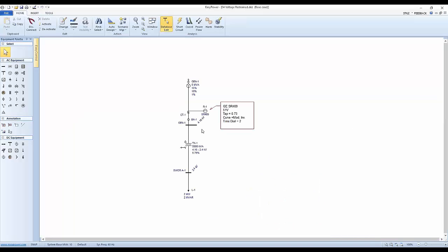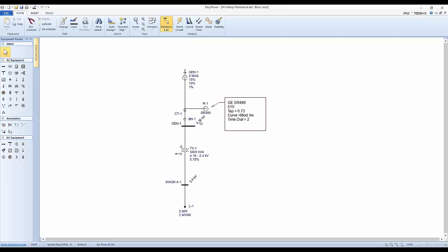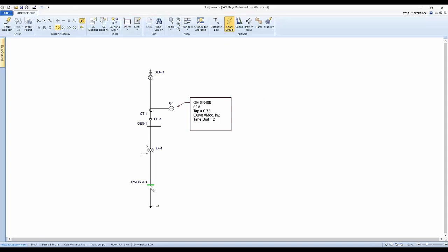There's another type of differential relay that's utilized when we have variable voltage, and very frequently this is used in a generator protection scheme. What it amounts to here is when I go to short circuit and fault this particular bus downstream, I may end up with some sort of a fault condition that's dependent upon the variations in the settings because of the voltage sensitivity.